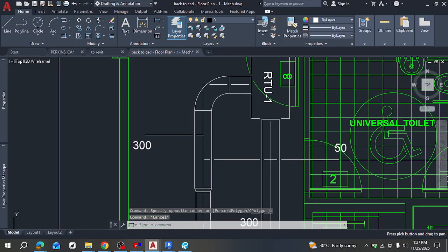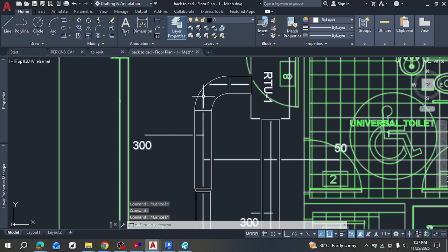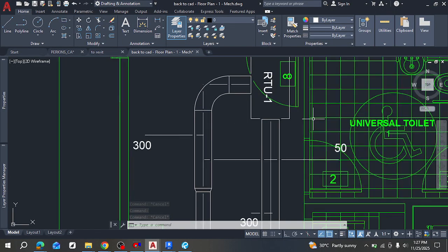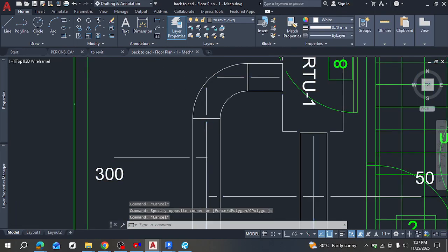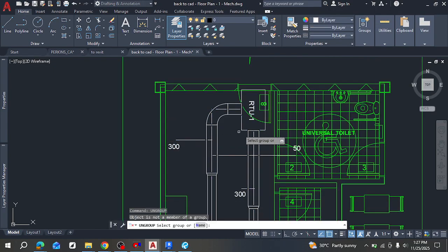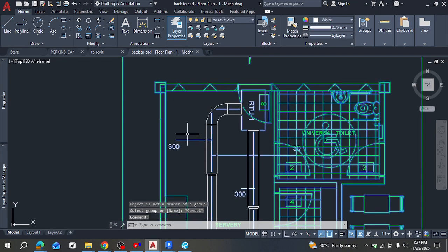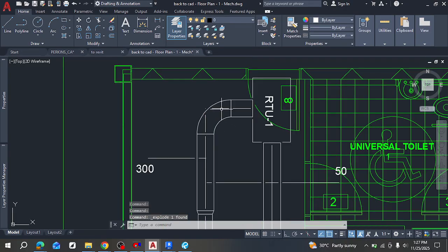So if you notice now, I can delete those initial ones. Oh, remember this thing is still grouped. Yeah, everything is grouped except what this duct just brought in. So I will just ungroup it. Yeah, as it comes out of Revit, it's usually okay. Let me explode it instead. So this is explode. So now it's on its own. So now I can select each individual one and delete them, to make sure that my work looks good and presentable.